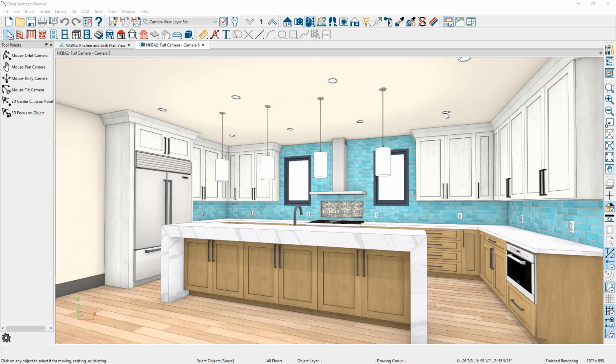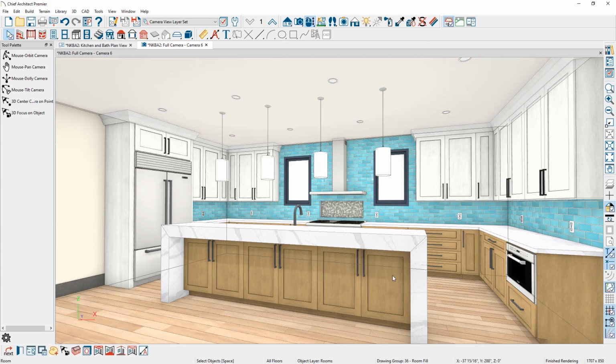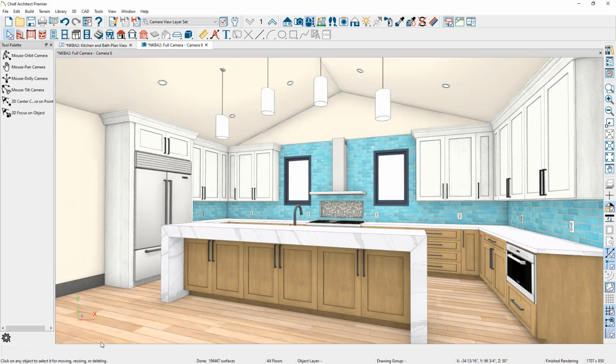Let's pretend in our first scenario that the client wanted to see a vaulted ceiling. What we can do is remove the ceiling planes in the plan, and the ceiling will instead follow the roof pitch. So if I click in the room and then I come to our tools in the bottom left hand corner, there's going to be an option that says turn off ceiling. And if I click on that, you can see how the room vaults, and now we have a cathedral style ceiling. And you'll notice that our can lights, they're regenerated to be in those ceiling planes.